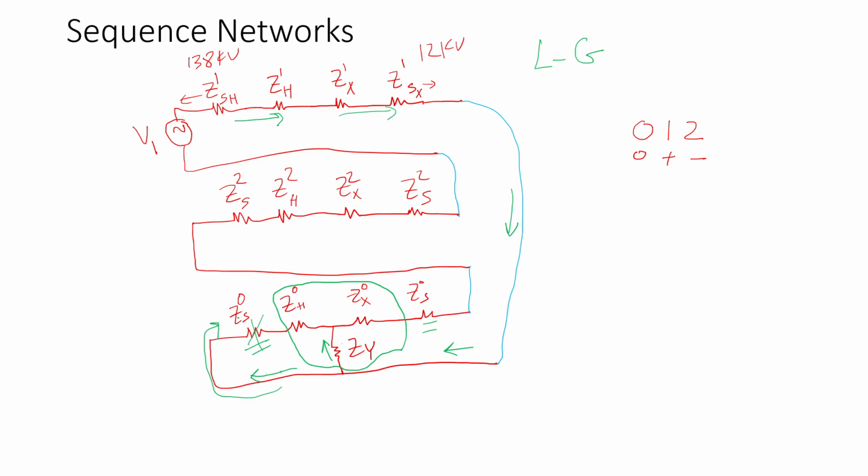And these system impedances, the zero sequence system impedances, can be from 3 to 5 times the system positive sequence impedance. Obviously, the further you go away from the source, the larger those impedances get. So they are very critical in the sizing or the design of this stabilizing winding and also the main windings when it comes to line to ground fault.